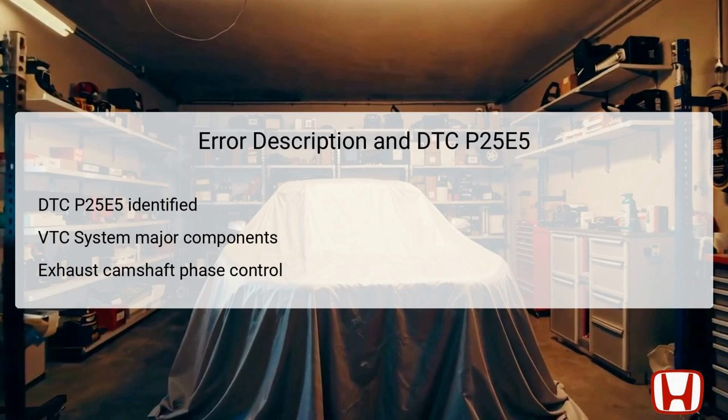The DTC P25E5 signifies a malfunction within the Variable Valve Timing Control B system, triggered by a noticeable discrepancy in the phase relationship of the exhaust camshaft. When the PCM detects that the actual phase does not align with the phase command, it records this error code. The VTC system primarily consists of the variable valve timing components like the VTC solenoid valves, specifically valve B, and the control passages. The camshaft's position is crucial because the exhaust camshaft controls the timing for exhaust valve operations.